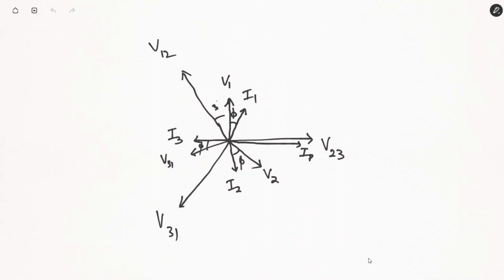IP V23 is the voltage that is applied to the pressure coil. I am saying that it is connected through a very high series resistance. Actually, the load will affect the phase between IP and V23. But since it is connected through a very high value of resistance, IP will be almost in phase with respect to V23. It's almost parallel to V23.